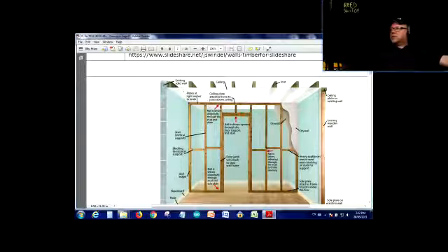But you have to know that sometimes you're going to have the joists here in the ceiling that are going to run against you, right? So if you just make an opening here in the drywall and you try to run the wire this way, then obviously you're going to encounter some sort of big time problems here, right? So just so you know that.